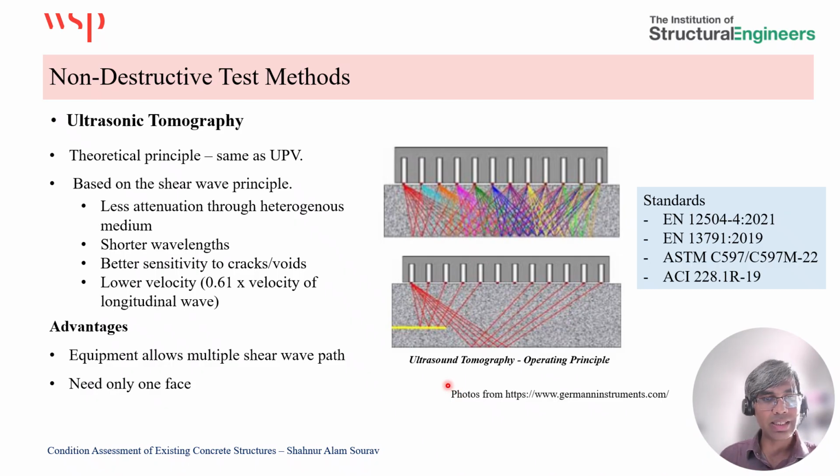Another thing to notice is that this shear wave principle works better because there is less attenuation in the concrete, being a heterogeneous material, and also this has better sensitivity to any cracks or voiding.